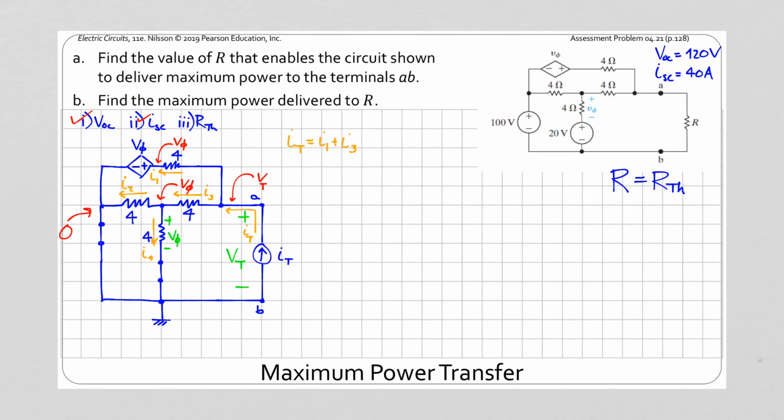So my test current flows in, and I've got I1 and I3, so my test current is going to break off to be those two values, and I can see that's going to depend on V phi, and so that's another variable I'm going to need to look at right here. And what I've got is I3 is flowing in, and I've got I2 and I4 flowing out of that node. I'm going to go ahead and write my equations.